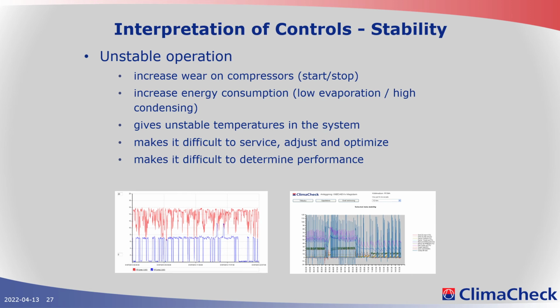Then we come to the interesting part: the chillers and heat pumps are not, in most cases, working at the absolutely best. But the main problem is not because of problems in the chillers or heat pumps or refrigeration racks. It's because the conditions are not as they should be. So we see a huge number of systems where there are way too many starts and stops. We see many systems with fixed chilled water temperatures that are absolutely not necessary.